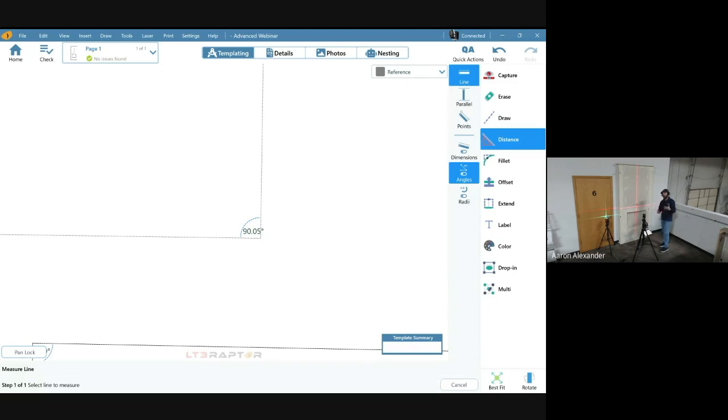So the tolerance we're really looking for here is to be within 0.15 degrees of 90. So that means the number I'm looking for is 89.85 to 90.15. Okay, so that's 0.15 degrees plus or minus from 90, us checking our accuracy here. Now, if we're on the outside edges of that plus or minus 0.15 degrees, that's perfectly fine for, say, full height backsplash. Some smaller runs, we're only dealing with 18 to 30-inch tall backsplash pieces.